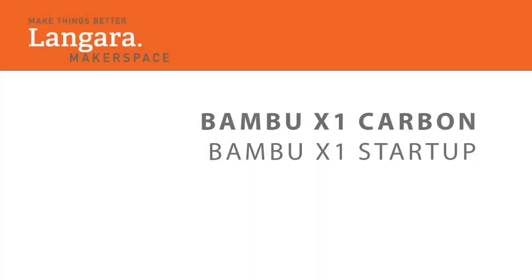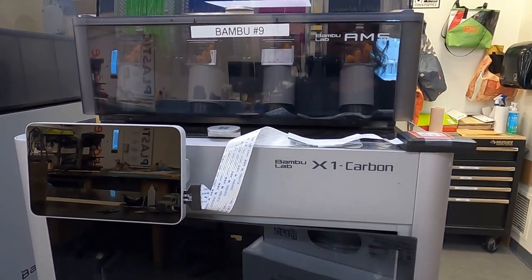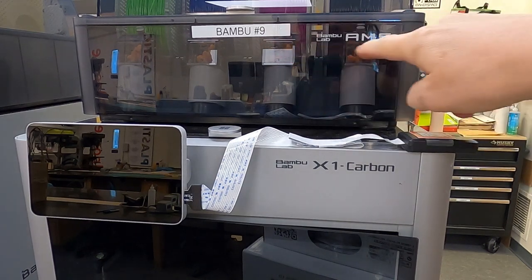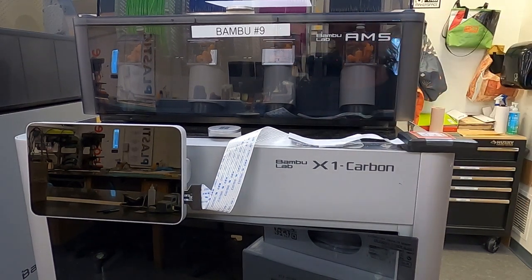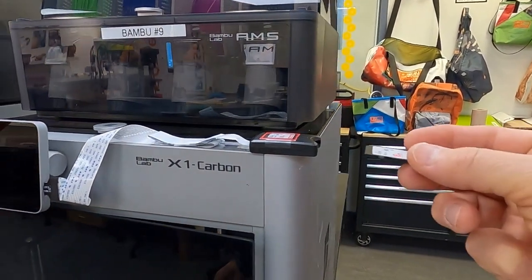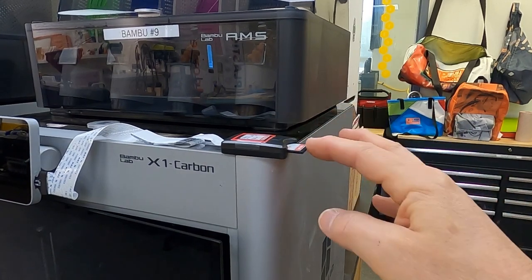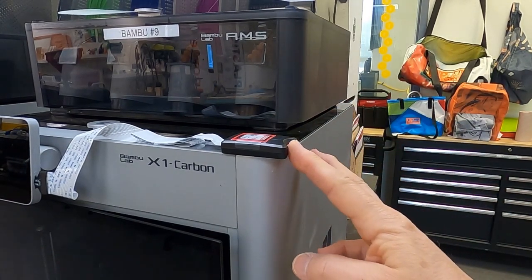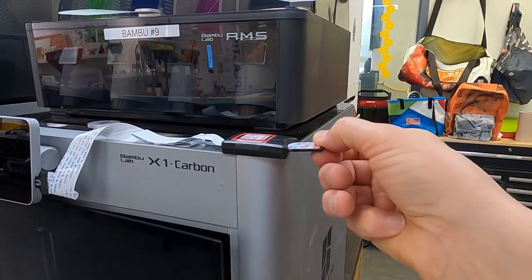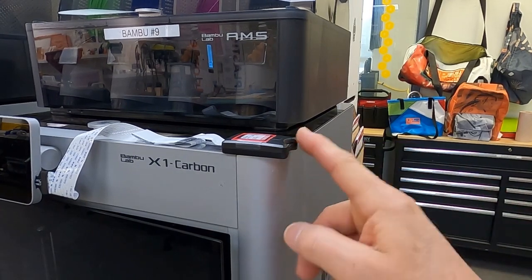Okay, we're now going to go to the Bambu printer, and you want to go to the one that you've signed up for. The number's on the AMS material loader. So this is Bambu 9. And now we want to take our SD card. The SD holder is on the top, and you want the label up. You want to gently push it in and let it pop back, and it's going to click. And it should be just under flush. Again, I'll gently push it in, it'll pop back and click. And just under flush.